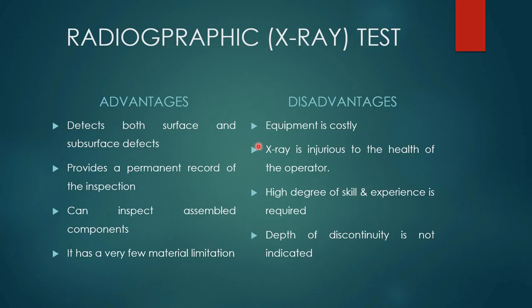Now next, disadvantages. Its equipment is costly. X-ray is injurious to the health of the operator because of its high intensity. Then a high degree of skill and experience is required for this radiographic test. And last, the depth of discontinuity is not indicated, as I discussed in the first point of advantages, subsurface defects. How deep it is, we cannot clarify.